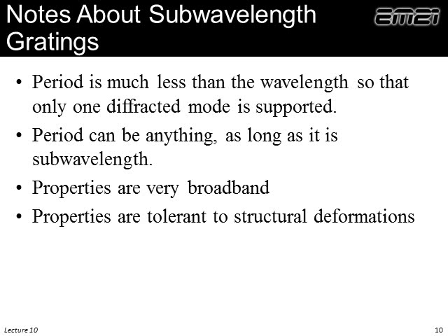So normally what I do when I'm designing these things is I make the grating period absolutely as small as possible so that I can still manufacture it and it forms well. But there's no way you can make it too small. It'll still work just fine. If those grating grooves are a billionth of a wavelength, it will have the exact same properties as if they're a 20th of a wavelength. So no problems there. They're very broadband.